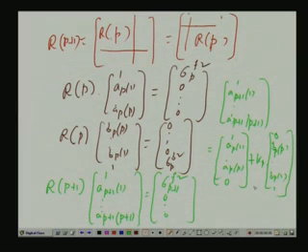My point is, I am just proposing, and let us verify that it is possible by a particular choice of k p. Can we write the p plus 1th order forward predictor coefficients as a linear combination of the pth order forward predictor and a 0, and a pth order backward predictor and a 0 on top? Can we do like this?